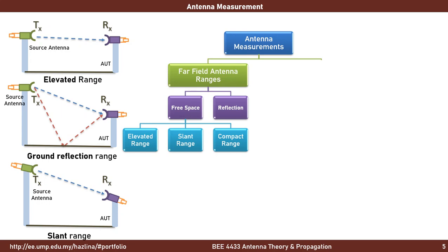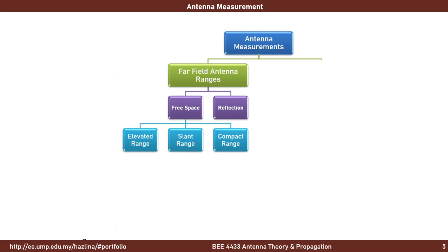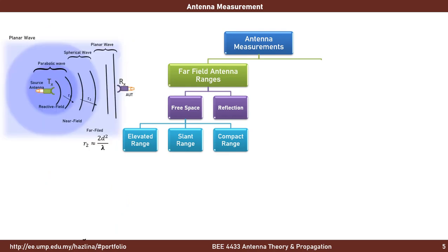Note that antenna measurement requires that the antenna under test be illuminated by a uniform plane wave. This requirement is achieved in the far field range, which in many cases dictates large distance. A compact range creates a plane wave field at distances considerably shorter than those needed under conventional far field criteria.